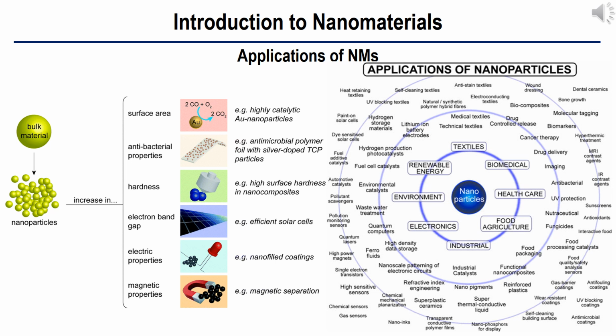However, there are several technological impediments to these advancements, including lack of ultrafine precursors to manufacture these components, poor dissipation of the tremendous amount of heat generated by these microprocessors due to faster speeds, short mean time to failure, poor reliability, etc. Nanomaterials help the industry break these barriers down by providing the manufacturers with nanocrystalline starting materials, ultra-high purity materials, materials with better thermal conductivity, and longer-lasting, durable interconnections, connections between various components in the microprocessors.